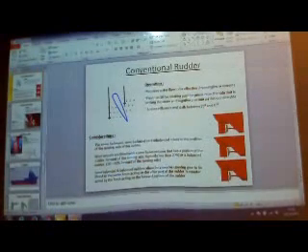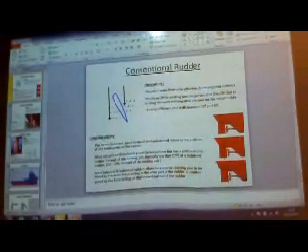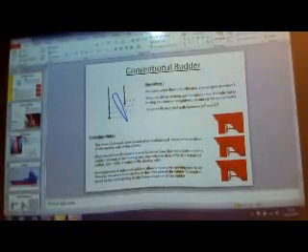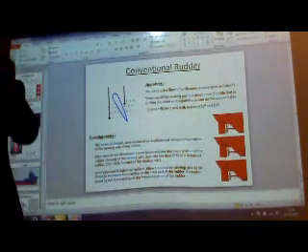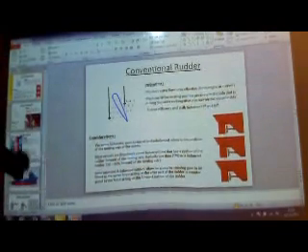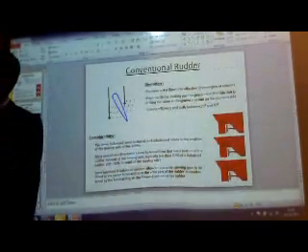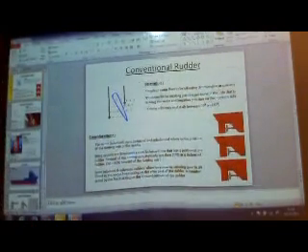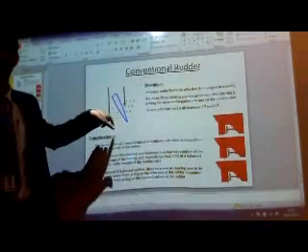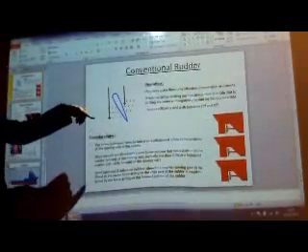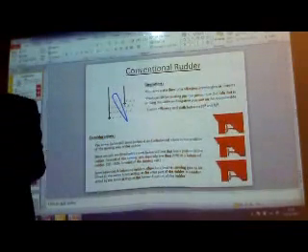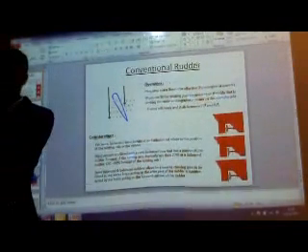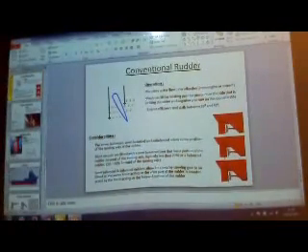Make sense? So it's a give and take. You will have to decide what you want to do based on your needs. So common sense: if you are propelling out at sea, in open sea, at higher maximum RPMs or maximum engine efficiency at maximum vessel design speed, then you are not going to be moving about a lot. You don't need to move about a lot to get the direction. Why? Because high velocity of water is passing through it, even the slightest deflection will create the required lift that you need.